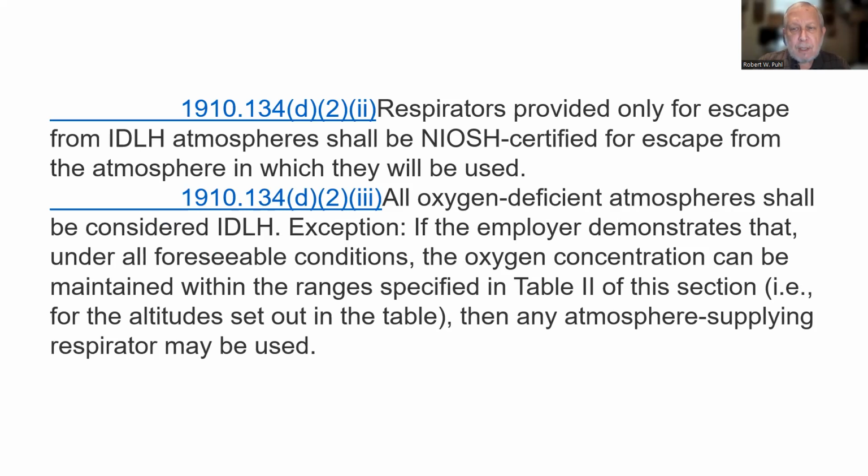All oxygen deficient atmospheres shall be considered IDLH. Now, as an exception to this, if the employer demonstrates that under all foreseeable conditions, I don't know how you do that, the oxygen concentration can be maintained within the ranges specified in Table 2 of this section, in other words, for the altitude set out in the table, then any atmosphere supplying respirator may be used. We'll look at the table here in a second.